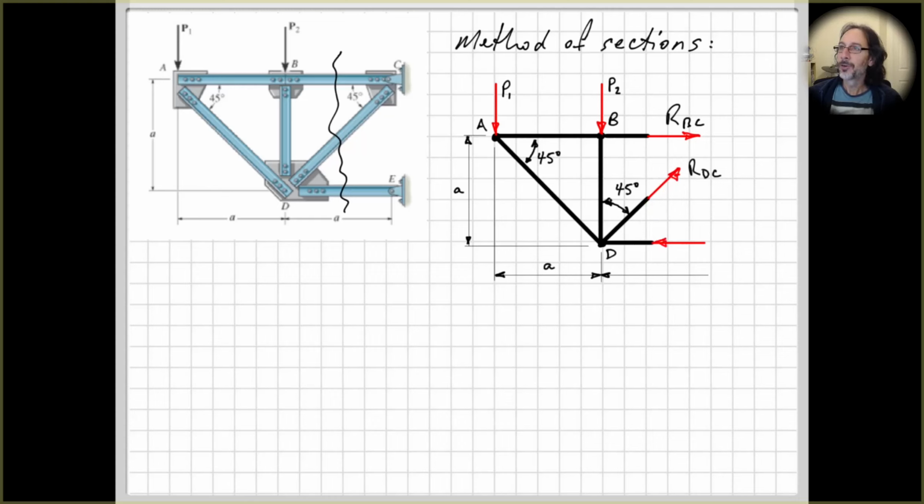I'll label that other force first. Right, so this one down here acting to the left. So that's how we determine our internal forces that are acting in each of the members. If you can't do the thought experiment by looking at moments to work out your force to start with, then just make them all positive or tension, and then your algebra will tell you which ones are in compression.